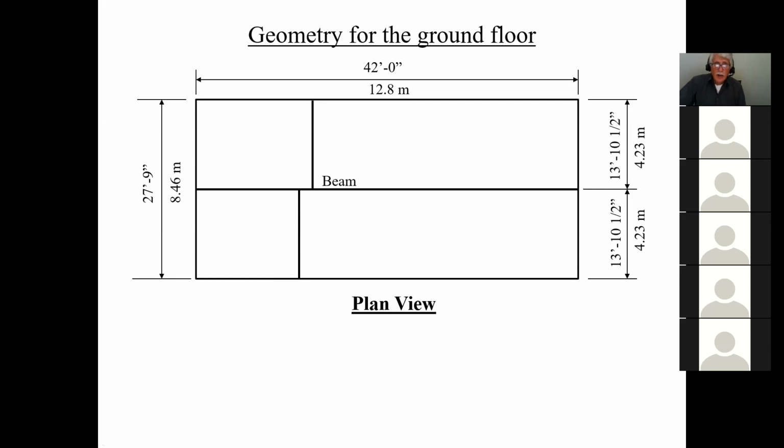What you have to decide now is that we're going to be putting a built-up beam here because, in cheap residential construction, built-up beams are what most people use. This way, when you order your joists, you order up the joists for the built-up beams, and it all gets delivered from the same lumberyard instead of you ordering a special glulam or parallel lam. So usually the built-up beam is the way that you go, unless you need super big spans, in which case you might decide to use a steel beam. But this is okay.